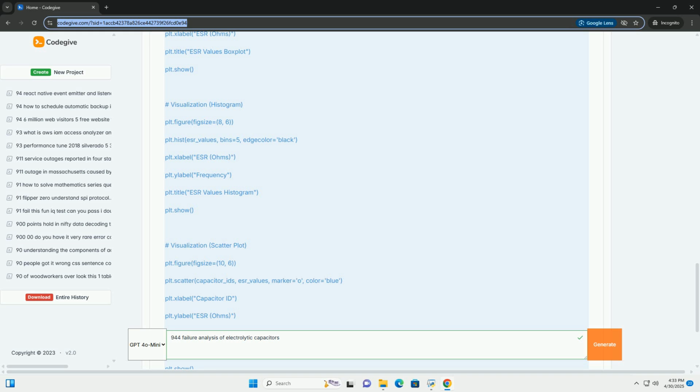7. Bulging/rupture. Description: the capacitor case bulges or ruptures, often accompanied by electrolyte leakage. Cause: excessive internal pressure due to gas generation from electrolyte decomposition, often caused by overheating, overvoltage, or reverse voltage. Symptoms: visually obvious damage, electrolyte leakage, a strong odor. Impact: complete failure of the capacitor and potential damage to surrounding components from the leaked electrolyte, which can be corrosive.